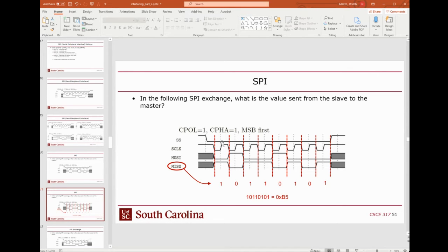So I drew my own dotted lines on the falling edge of the clock because the data is stable on the rising edge of the clock in the middle. It's kind of easy to see once you look at where these lines are. I'm just drawing vertical lines wherever the data may potentially change. Now, if you look over here where my mouse cursor is, we have two consecutive zeros on MOSI and two consecutive ones on MISO. So the data isn't actually changing there, but yet we still have this line that separates those two consecutive bits. So what's the trick here?